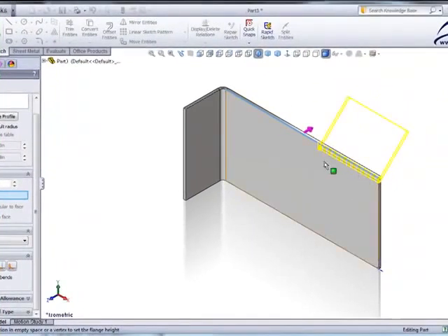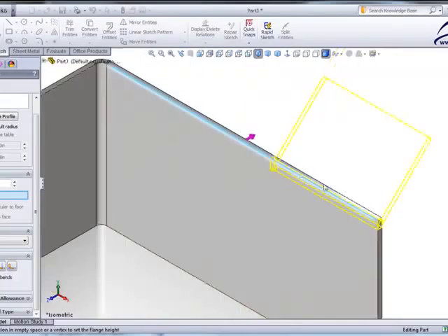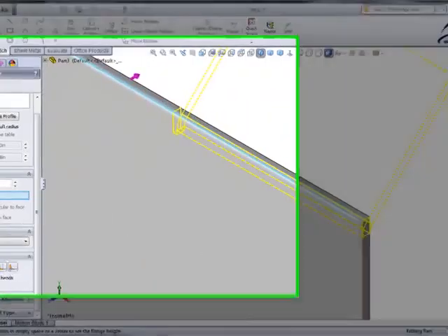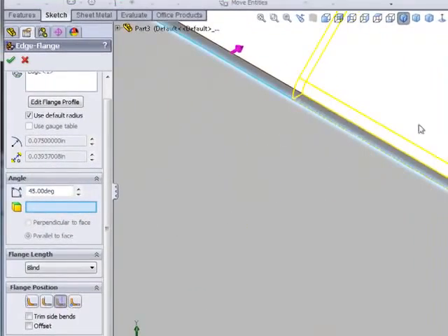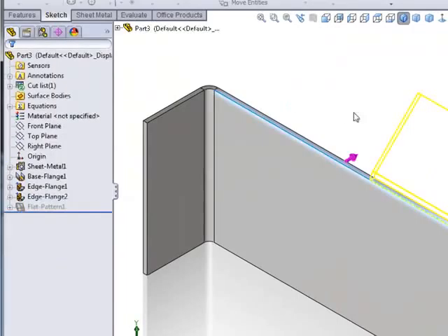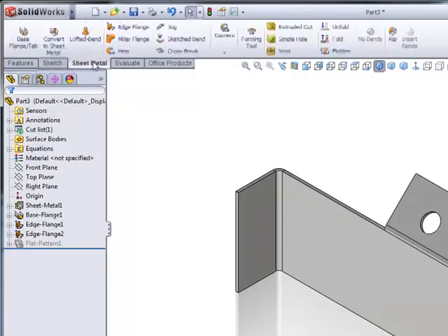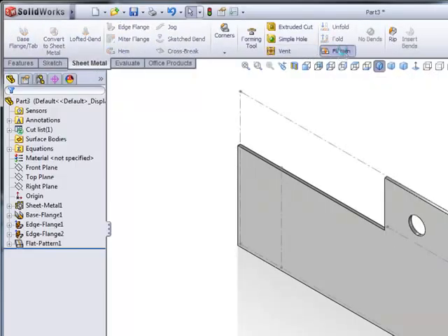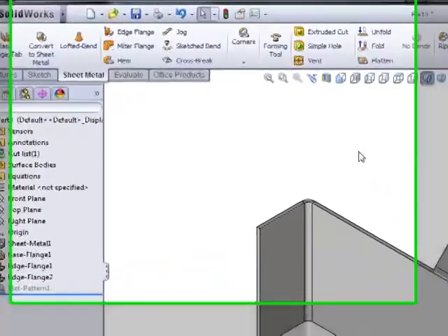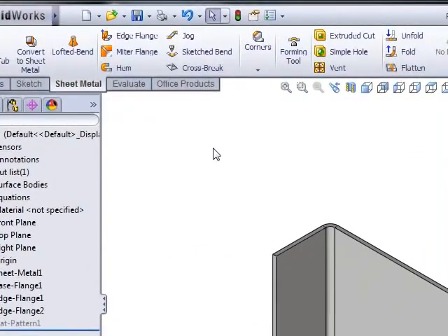And then the material, you can see there's an automatic relief being put in there because of where the position is, and maybe I want to actually put the bend to the outside so it doesn't make a relief. I'll pick OK. So now I have an extra flange in there, and again I can flatten that, toggle back and forth. We see in 2011 that it puts in what the bounding box for the blank material shape would be, square size anyway.